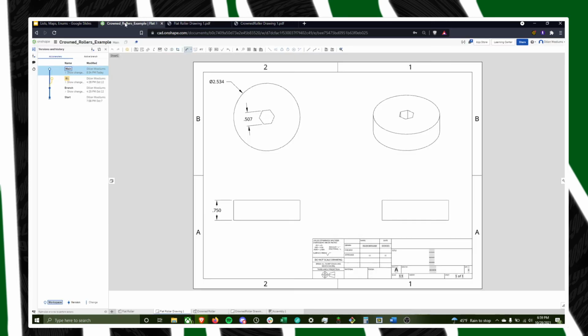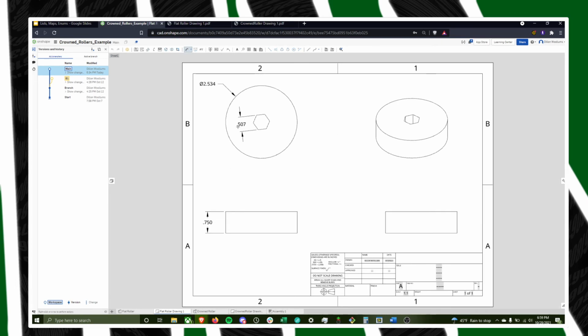This is really handy for any kind of sheet part. A lot of times we laser cut Lexan, but sometimes it's something that won't fit in the laser, or we're cutting a simple piece of aluminum or something. You can put a drawing in here in 1 to 1 scale, literally tape that, cut the drawing out, tape it over the part, and just manually cut it out really quick because it's in 1 to 1 scale. Drawings are really important.